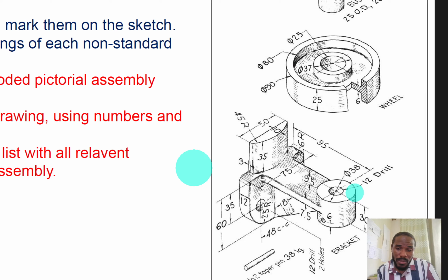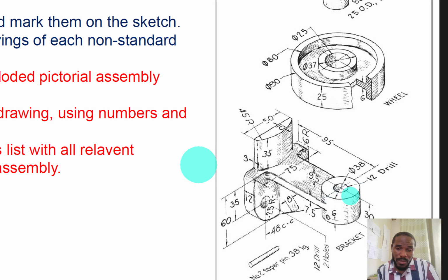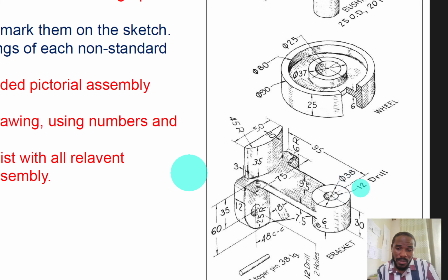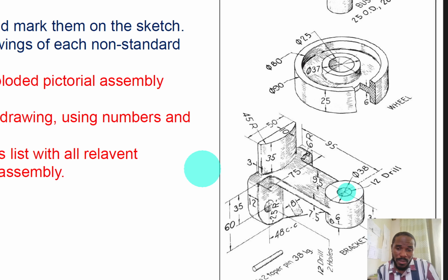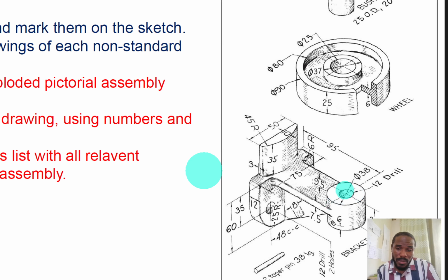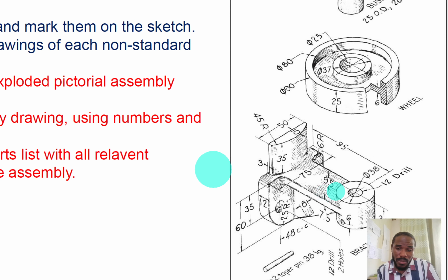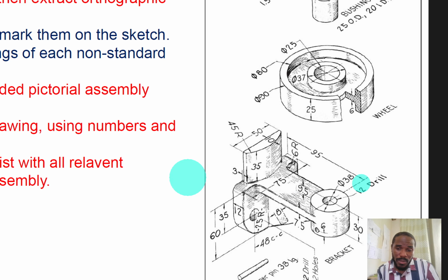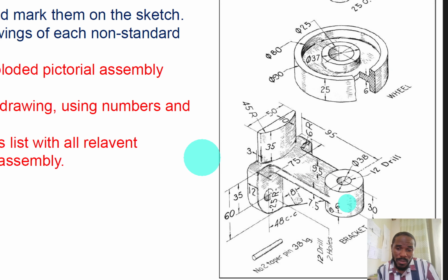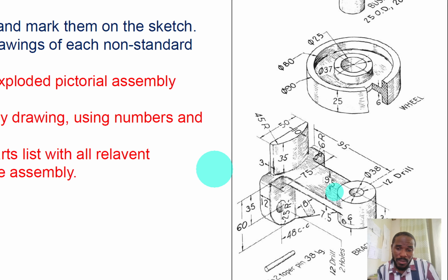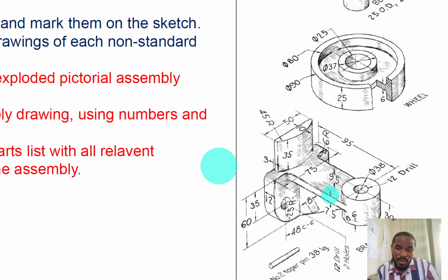Now, the next feature to do is this cylinder. Okay, it's very, very simple. Okay, the outer diameter is 38, the inner diameter is 12. All of them are bang on located at the middle. So we get to the midpoint of the edge of this feature we just drew, and we draw those 2 circles, and then we extrude. Now, but follow the extrusion system. It's extruded up by 9.5. Okay, from that face upwards by 9.5, right?